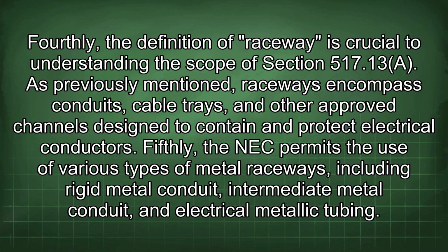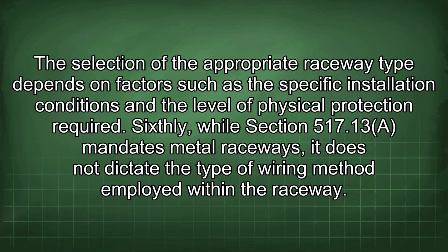As previously mentioned, raceways encompass conduits, cable trays, and other approved channels designed to contain and protect electrical conductors. Fifthly, the NEC permits the use of various types of metal raceways, including rigid metal conduit, intermediate metal conduit, and electrical metallic tubing. The selection of the appropriate raceway type depends on factors such as the specific installation conditions and the level of physical protection required.